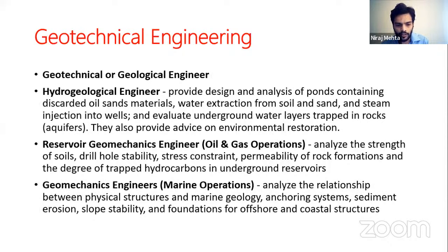So for a geotechnical engineer, there are multiple substreams. The person can be a geotechnical or geological engineer. The person can be a hydrogeological engineer. So what do you mean by hydrogeological engineer? They provide design and analysis of ponds containing discarded oil sands material, water extraction from soil and sand, and steam injection into wells, and evaluate underground water layers trapped in rocks, which are aquifers. They also provide advice on environmental restoration.